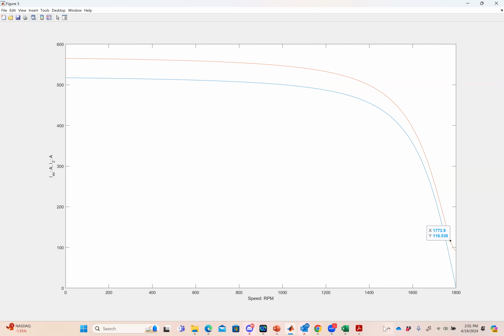All right, now what do I see about this here as I go down towards 0 speed? It levels out. But it levels out at what? Yeah, it levels at a very high current. In fact, I see that at the rated condition, this guy's about 116 or so. By the time he's up there, he's almost a factor of 6 higher, right? He's getting close to 600 amps there, right? So that tells me an important thing.